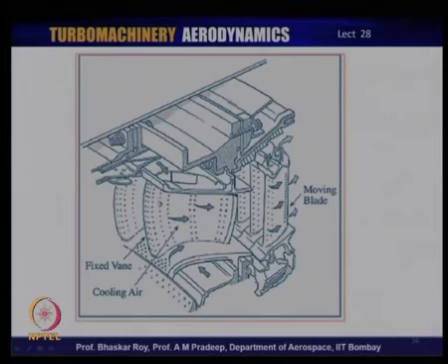As you can see, the stator has much more elaborate cooling technology. The modern rotors also have elaborate cooling technology on the rotating blades. So, this is the elaborate cooling technology that you need to do. Manufacturing these blades is an extremely costly affair, and each single turbine blade is hugely costly. It is entirely possible that one single turbine blade could be costlier than making a whole set of compressor blades. That is how costly the turbine blades are, because they have embedded cooling technology inside those blades.